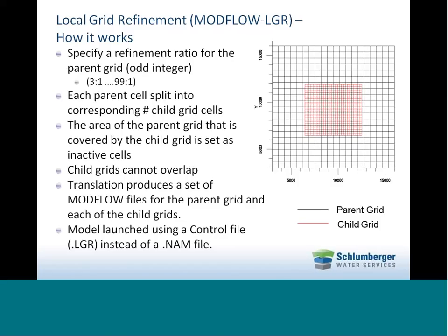The area of the parent grid that is covered by the child grid is set as inactive cells during the course of the simulation. A few drawbacks are that the child grids cannot overlap, and also the child grids must have the same angle of orientation as the parent grid. During the translation, this produces a set of Modflow files for the parent grid and an additional set of Modflow files for each of the child grids. The Modflow LGR engine is launched using a control file with the extension .lgr, and this is the alternative to what is typically done using the name file.